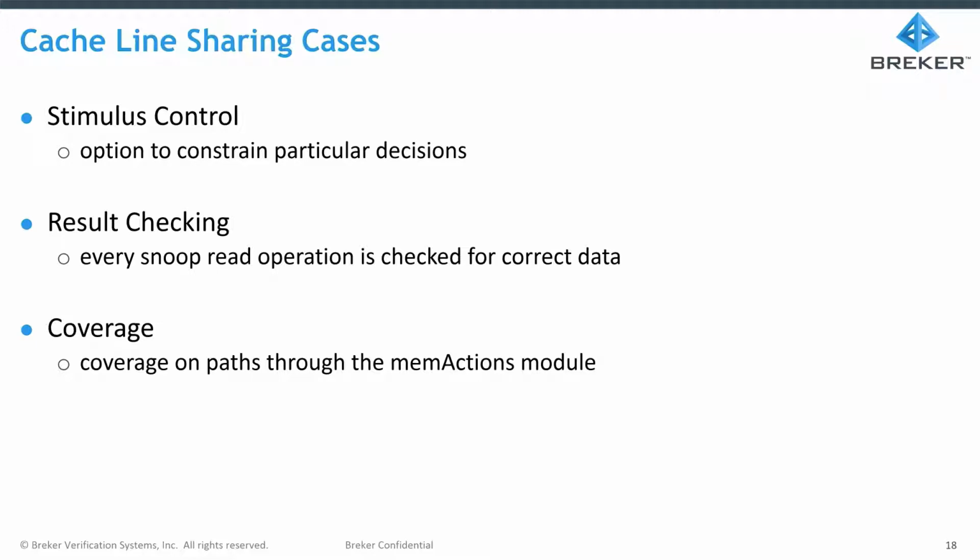We can control how many Snoops we want, whether they come from CPUs or external masters. Every Snoop will be data checked to make sure the return data is correct. And we can measure how often we have gotten Snoops from various agents.